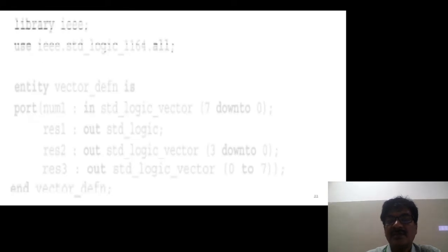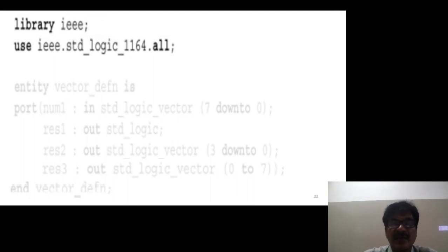Of course, before going to discuss these operators, see once the example on the data types and data objects. First of all, for every VHDL program. Previously we have seen an identifier, data types, data objects. What are the syntaxes for those? With some examples we have seen, and now how they can be used in the program, that we are going to see with this example.